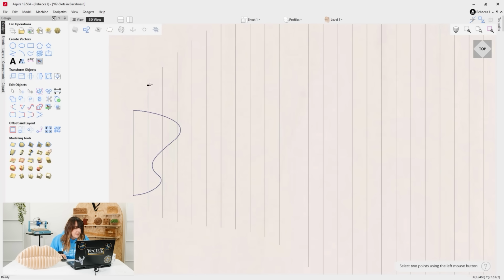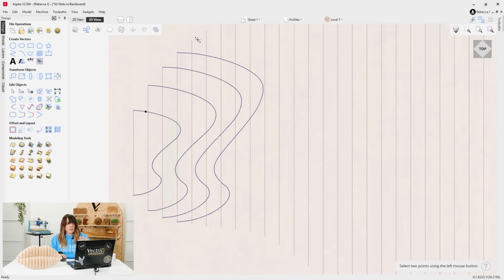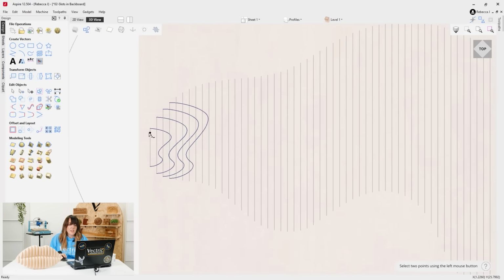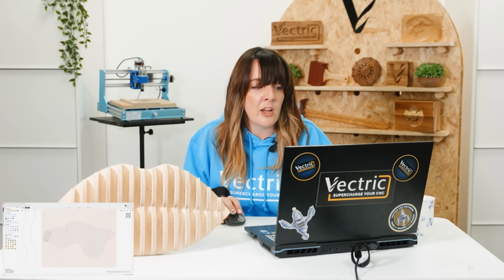Create cross-section vector, click, and make sure you snap to the bottom. Those crosshairs are important to see here. And again, because we've got those lines drawn in, we know that we're going straight down. We've got a nice straight line there, and everything should line up perfectly. The idea is we're going to use these shortly to join them to create our profile sides, okay? At this stage, we'd carry on and do this for probably another 3 minutes.